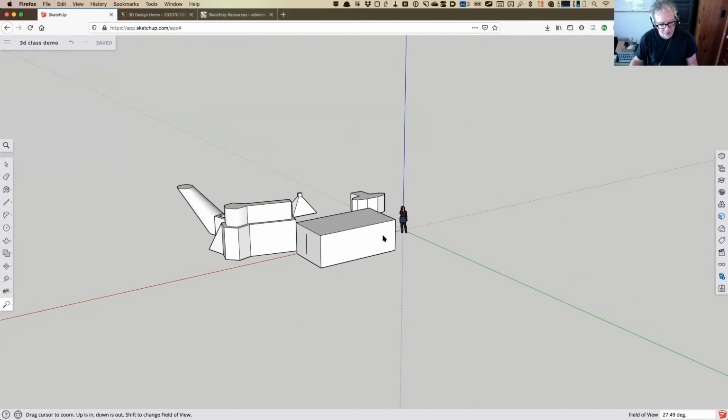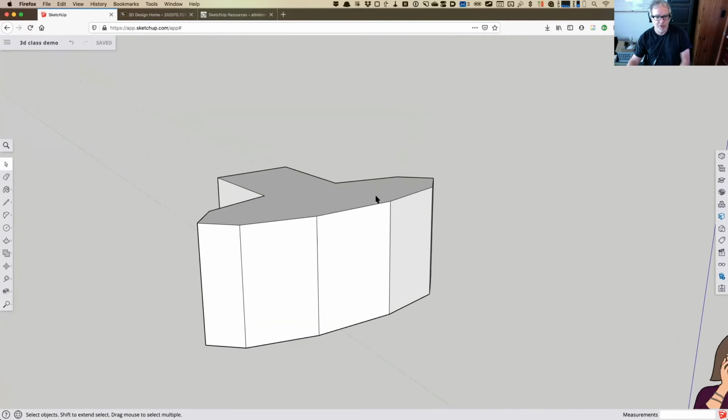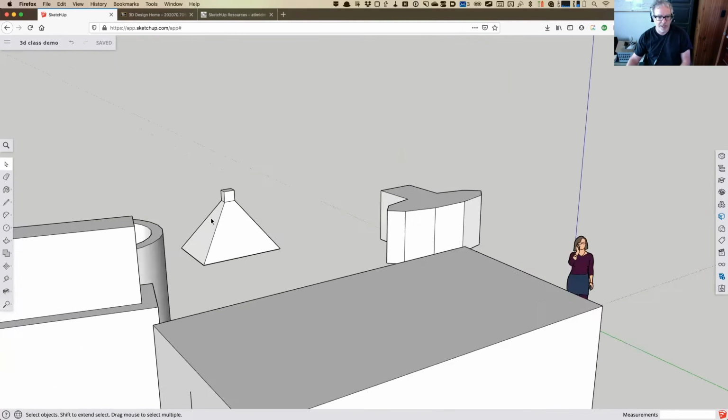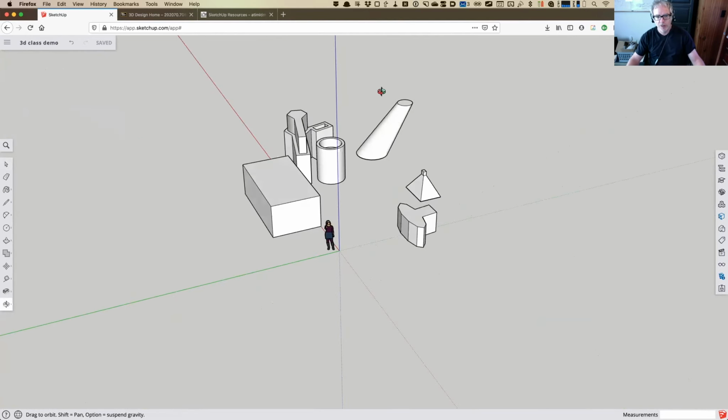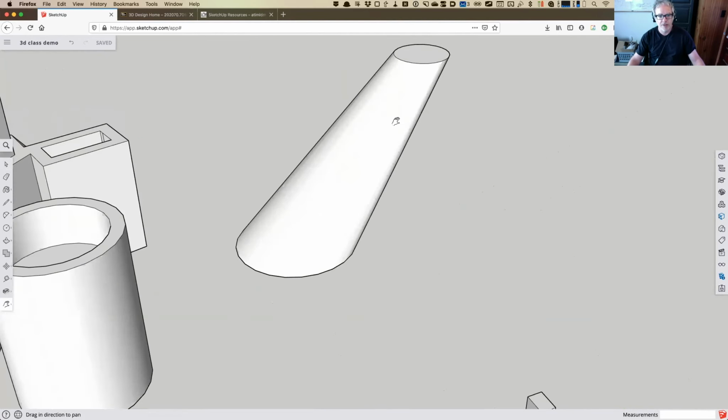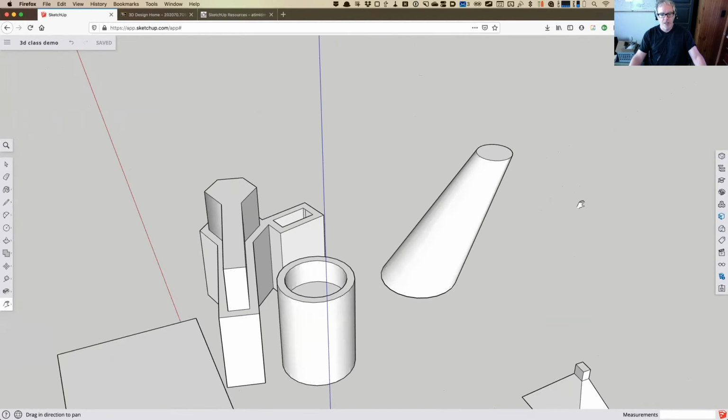So normally what I do, and you'll probably find yourself doing this, is just use the scroll wheel on your mouse or the two-finger scrolling gesture on your trackpad. And what that will do is allow you to zoom in to where your pointer is. You see, I zoomed into that shape by putting my pointer over it and then using my finger to scroll on the mouse. If I wanted to come over here, I can zoom into that shape. Okay. So really what I like to do is use the orbit tool and then the zoom tool and then the hand tool to position what I want.